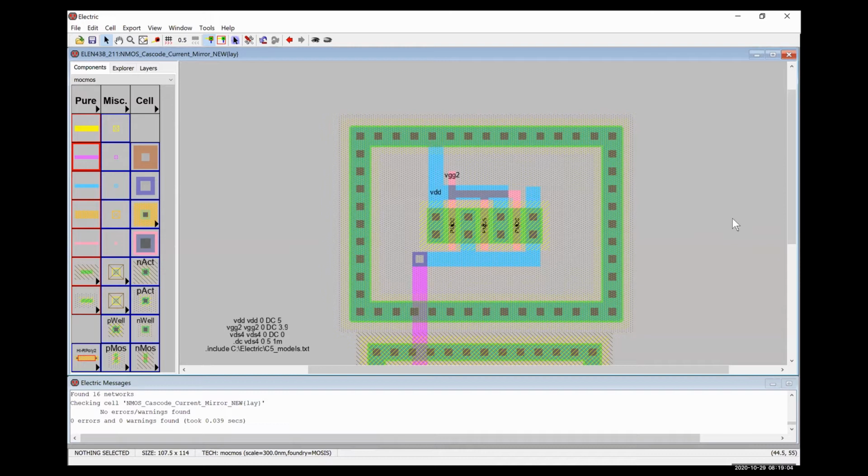No errors. So I've explicitly defined this whole entire region to be one large N-well. And I bet now that I've done that, I could make my ring slightly smaller, but I'm not going to go through troubleshooting all those errors that are going to come about from that.